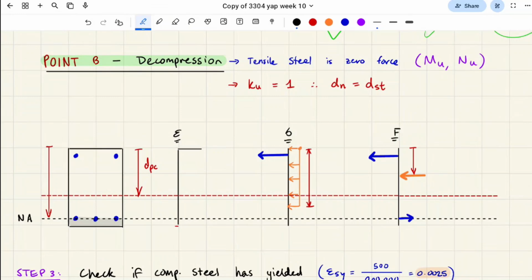Can you say that again? The neutral axis is defined as the point of 0 strain. So it would just have a diagonal line down to the neutral axis? Yep, it's like this. What about this point? That point is the maximum compression, which is compressive strain. Do you remember what it is? It's always 0.003. Very good.